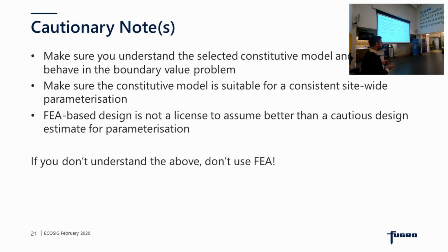So some cautionary notes on use of FEA, by no means extensive, but just some examples from my experience. It's critical that when you embark upon FEA-based analysis that you understand the constitutive soil model that you selected to represent your soil response and how that soil model behaves in the boundary value problem. Ultimately, that will constrain or dominate the prediction that you make, so understanding that is critical to really understanding how your results should be applied in design.